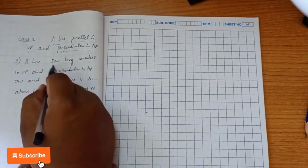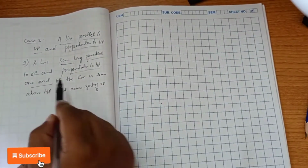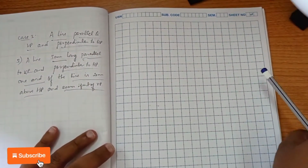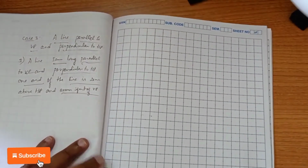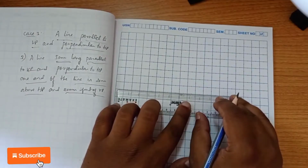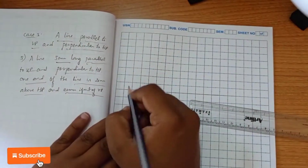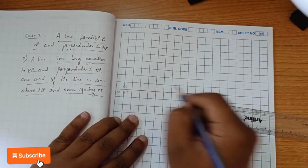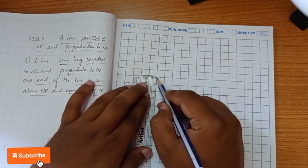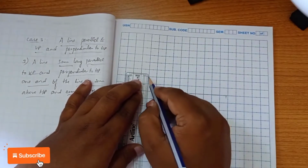Okay, we have to draw a line of length 50 mm. Here it is parallel to VP and perpendicular to HP. One end of the line is 20 mm above HP and 20 mm in front of VP. So first we are going to draw an XY line here. VP, HP and Y. Here both the ends of the line are at a distance of 20, so we can show the dimensions on one side.